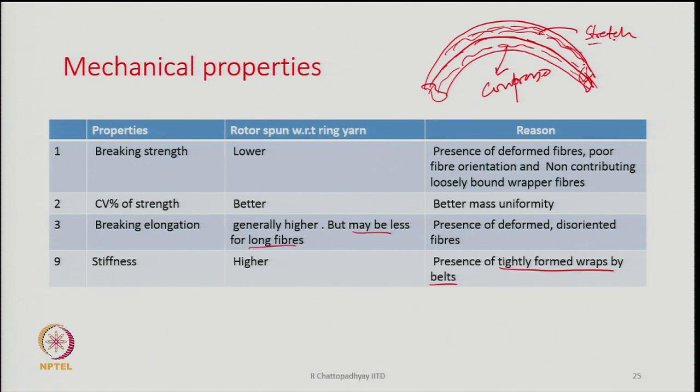So, they are going to stretch longitudinally and get compressed longitudinally also, and as a result there is going to be a lot of shear between the two groups of fibers. If the shear is allowed, that is, if we allow the fibers to slip over each other while their whole structure is going to bend, then the bending rigidity will be low.